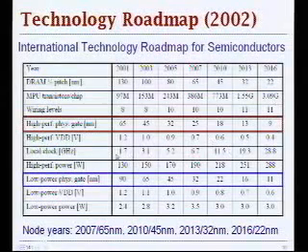So distributing this high frequency clock globally over a large die is going to be almost impossible. It's going to be a real problem. So you will have all of these machines working in isolation and performing operations locally, and then you will have a more global communication between all of these processing modules that occurs less frequently, because all the computation will be distributed across these processing nodes, and you will have to exchange the results of computation at a less frequent rate than the local clock.